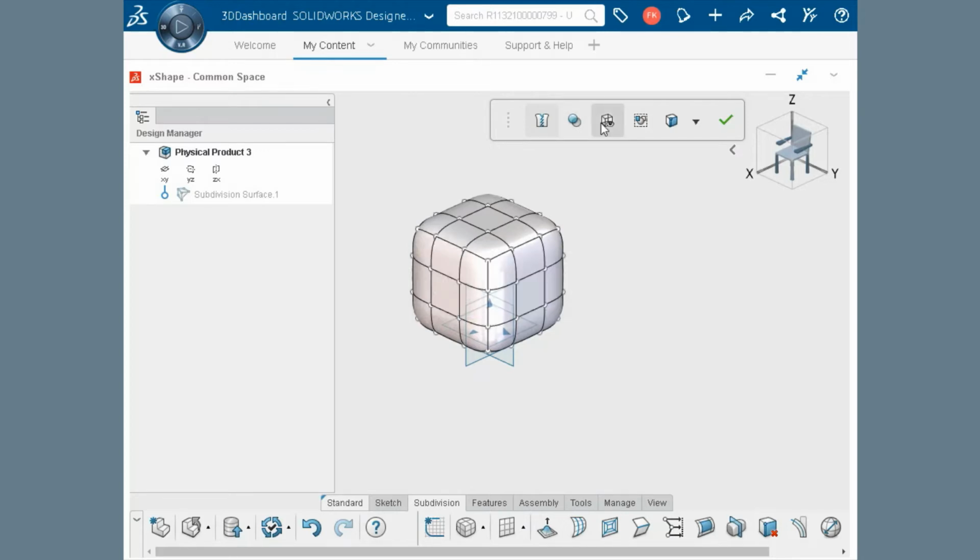At the top of the screen is the Subdivision Environment toolbar. It will remain on the screen while the subdivision surface is active and being edited. Although you can have many subdivision surfaces, only one can be active at a time. Click Show Mesh Cage to toggle on the control cage of the body. This option reveals the cage that surrounds the surface body. It is your choice to work with the cage on or off. We'll try it both ways, but for now, let's use the cage.